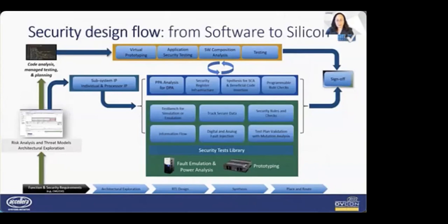In verification, we use solutions for tracking secure data and data leakage checks, fault injection and test plan validation with a security test library. And emulation for fault and power analysis, as well as prototyping suites, are the final stage of analysis before coming up with a final tapeout.